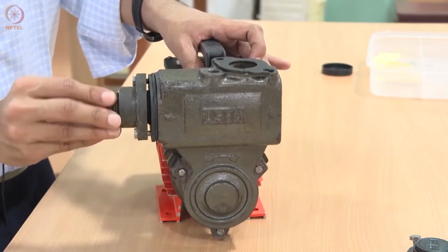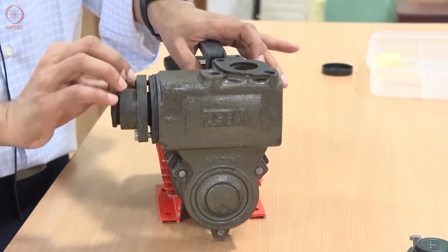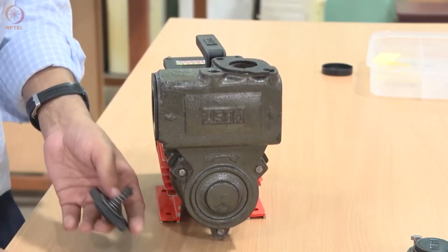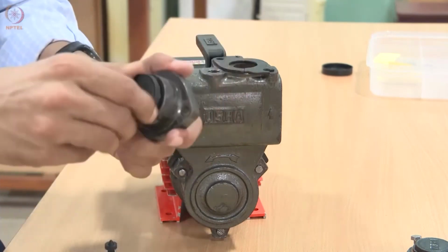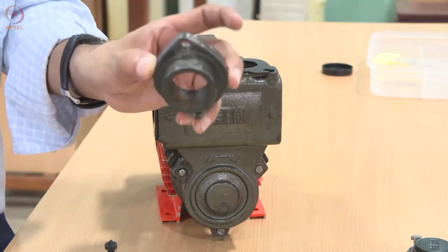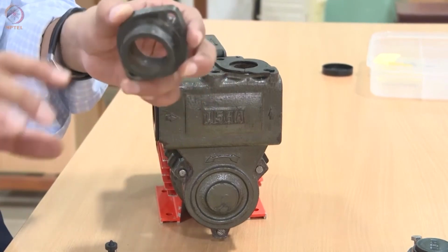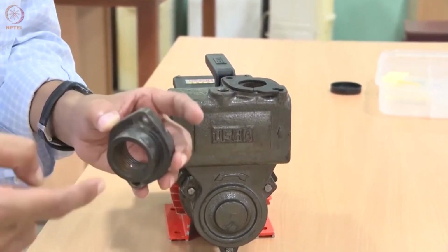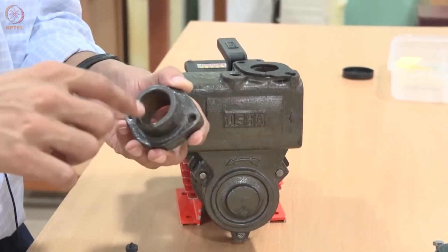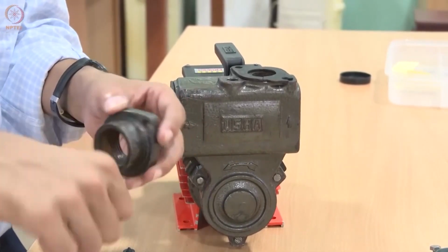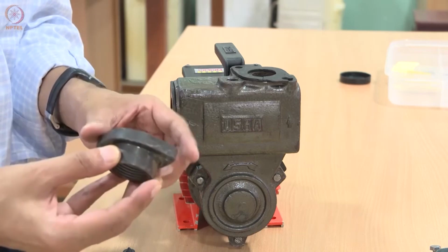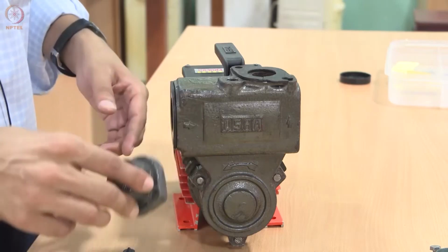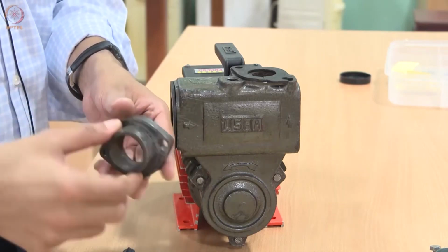Let me just remove this. Okay. This is what we call a flange. It is threaded. There is a female thread here, so we will connect a pipe here. This is a pipe thread, national pipe thread, NPT thread. It is a tapered thread which is self-sealing. You only have to apply a sealant, and when you screw in the pipe, it is self-sealing. The thread has a taper to it. If you observe carefully, there is a mild taper to it. That provides sealing between the pipe and the flange.